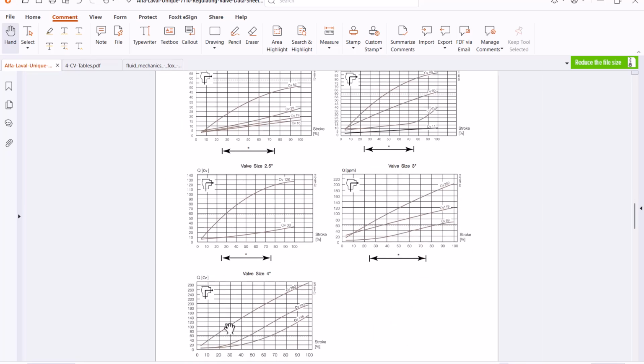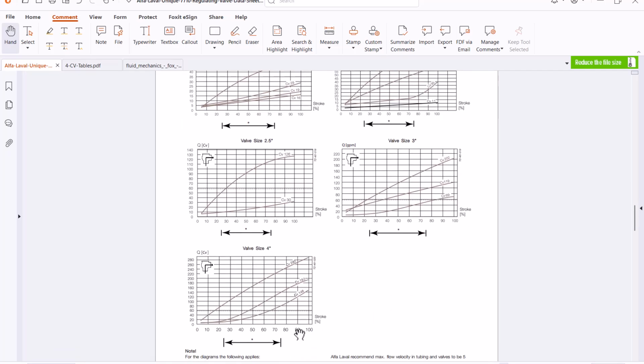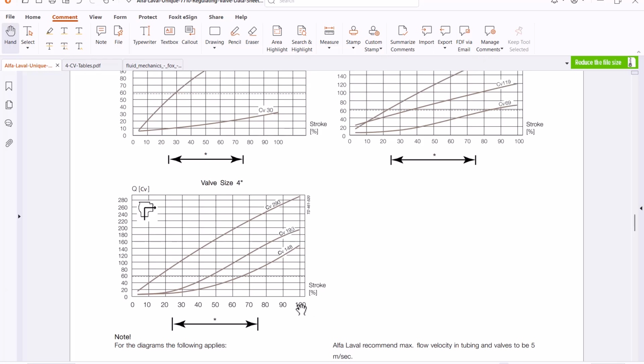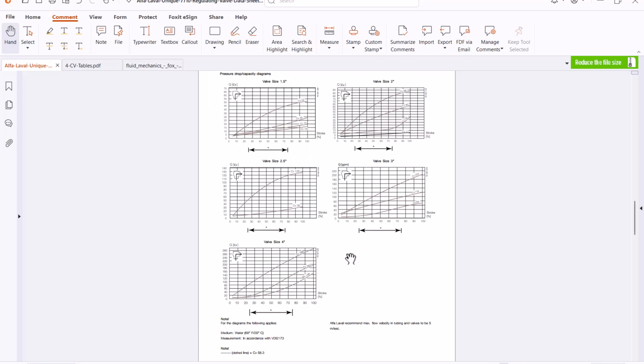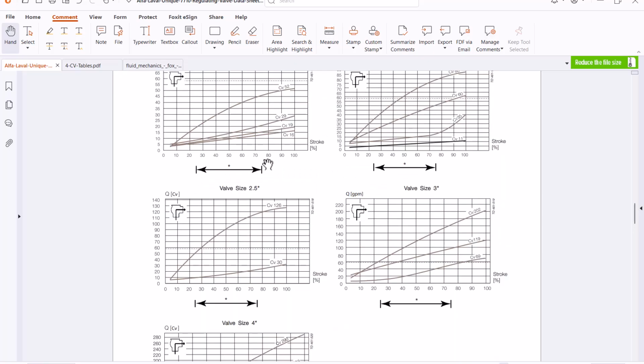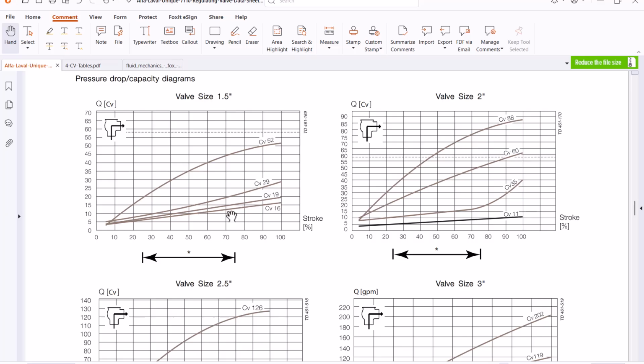And you can see that for different types of valves, if you open the valve, like here, 100% means 100% open, the flow coefficient is going to increase. It means that it takes a bigger flow rate to exert the same amount of pressure drop. And there are thousands of characteristic curves out there, and today we are not going to talk about how to select one of them. We are only interested in simulating one already chosen valve. So suppose I chose this one, and I want to talk about what this curve is going to tell us.